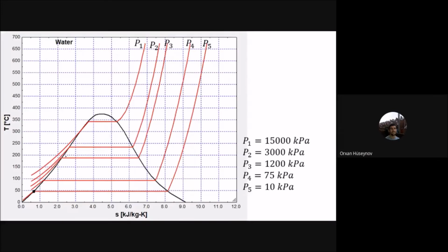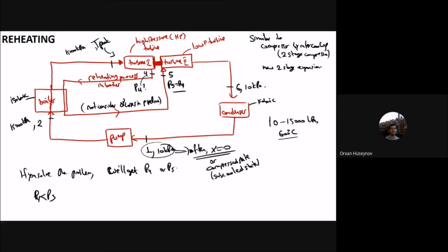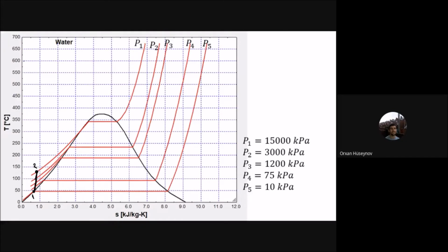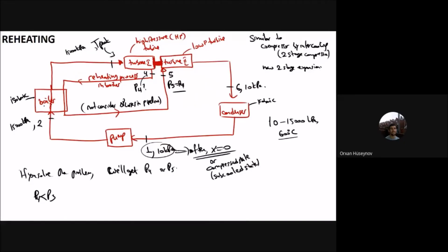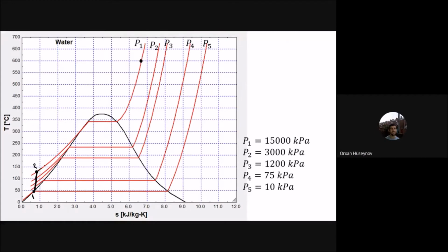So it will go in an isentropic manner to the last pressure line. So let me go there. Okay, and this is point 2. So you have point 1, and this is point 2, and it is the pump. Then from the pump, you have the boiler stage, and that boiler stage goes to a peak temperature of 600 degrees Celsius. This is point 3. You can see it: 600 degrees Celsius, with the same pressure line. So the boiler is isobaric. The pressure should be constant. So I draw that line here. This should be isobaric because it is the boiler.